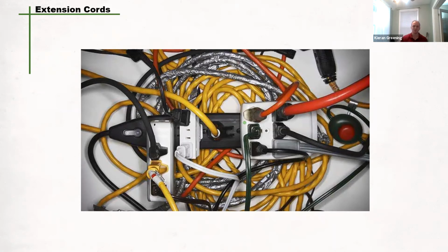As well, a common situation is if you have 50 feet from the power source to your tool, and you only have 2 25-foot extension cords that you're going to attach together. That is also a fire hazard. When you put the cords together, at the plug and the block, there's resistance. So the more times electricity has to flow through a different area like that, it will create heat, which in turn creates fire hazards.